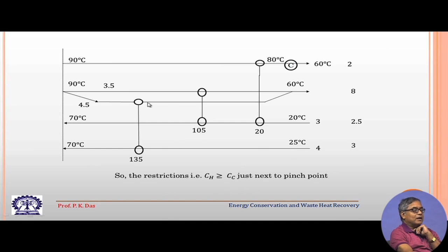Then we can think of the second heat exchanger. So, if we consider this heat exchanger, then this stream which has to reach 60 degree Celsius can be brought to 60 degree Celsius, we can tick off this. For the third, we can consider a match between stream 2 and this stream, that means this is another heat exchanger we can consider, and with this, the third stream can be satisfied.